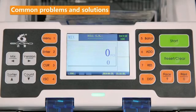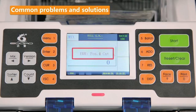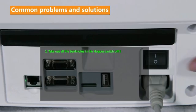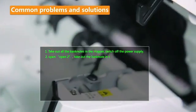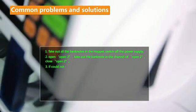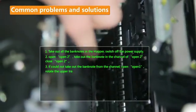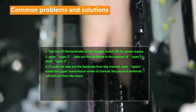1. Common problems and solutions. Banknote jammed. Troubleshooting. When the machine has a banknote jam, the display screen will display the prompt information. Do as the following steps. Take out all the banknotes in the hopper. Switch off the power supply. Open 2. Take out the banknote in the channel of open 2. Close open 2. If you could not take out the banknote from the channel, open 1. Rotate the upper transmission wheel of the channel. The jammed banknote will exit from the channel.